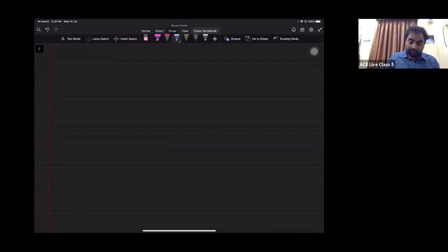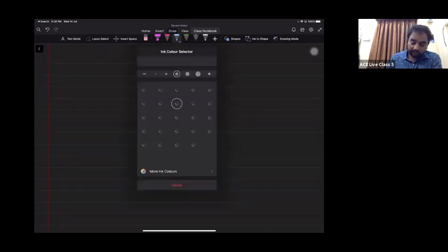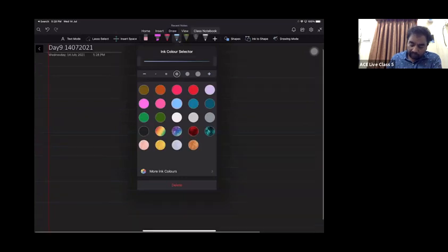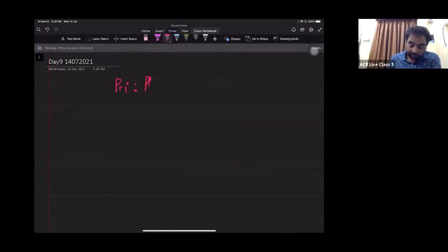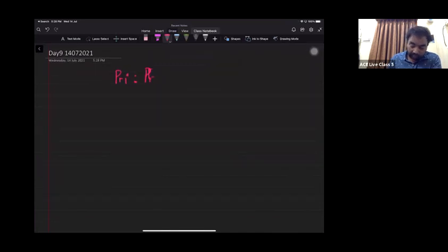Yesterday we were able to derive an important relationship between the rotor input, rotor losses, and the rotor output. What is that very important relation, if you recall? We used P suffix Ri for the rotor input, so rotor input, rotor losses, rotor output is equal to 1 is to S is to 1 minus S.